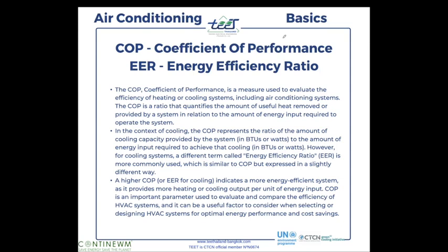In the context of cooling, the COP represents the ratio of the amount of cooling capacity provided by the system in BTU or in watts, what I was just mentioning, to the amount of energy input required to achieve that cooling in BTUs or in watts. However, for cooling systems only, a different term is called energy efficiency ratio. Okay, so they measure basically for air conditioning only, not in heating, but only in cooling. It's very similar to the COP. It's just expressed in a slightly different way.